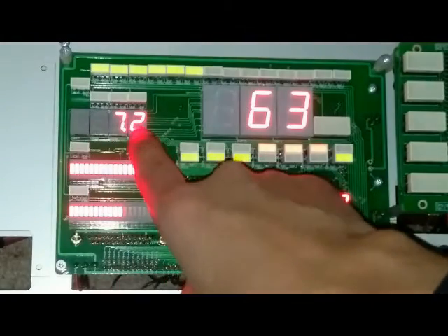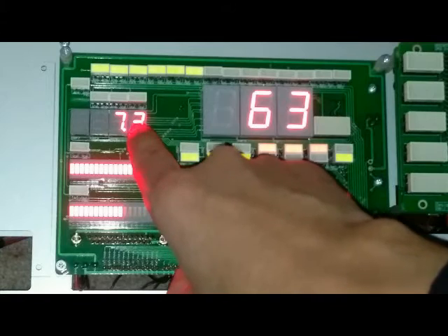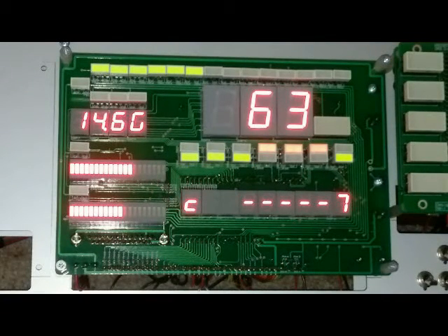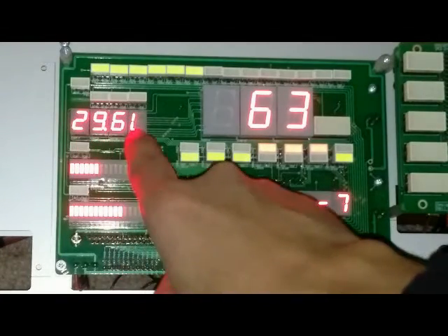This display here is normally used as a trip meter, but we can display a number of different functions which we can select by pressing a connected button on the outside of the unit. One press will give us a fuel display, which we can vary by changing a control on the test rig that we have hooked up to this. So that's showing fuel in gallons, and we also have that parameter being displayed on this bar gauge right here. If we want to change the units of fuel from gallons to litres, we just push and hold a button, and now we have the fuel display in litres.